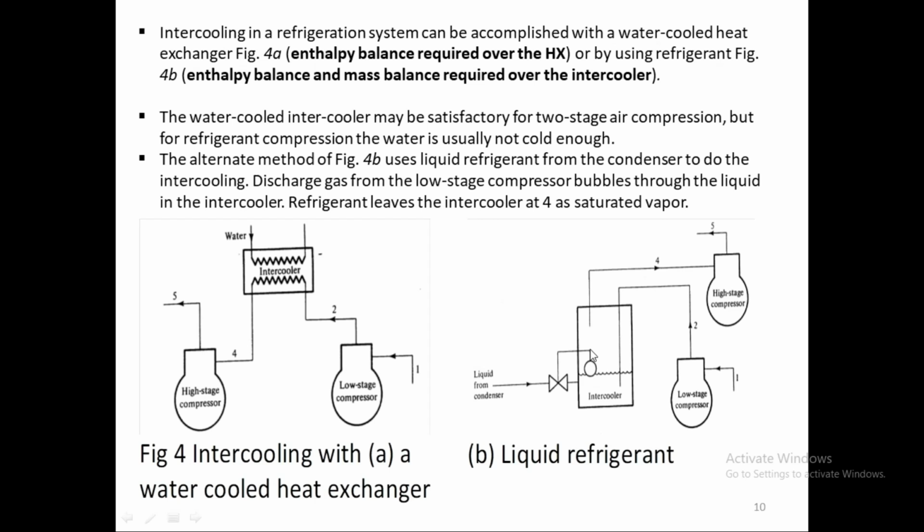So we have a complexity here. It is not just whatever is coming out of this low stage compressor going into this high stage compressor. We have an additional amount of vapor which is coming from here, which we have as flash gas removal, or the flash tank already has it. So that is why we have to apply a correction.